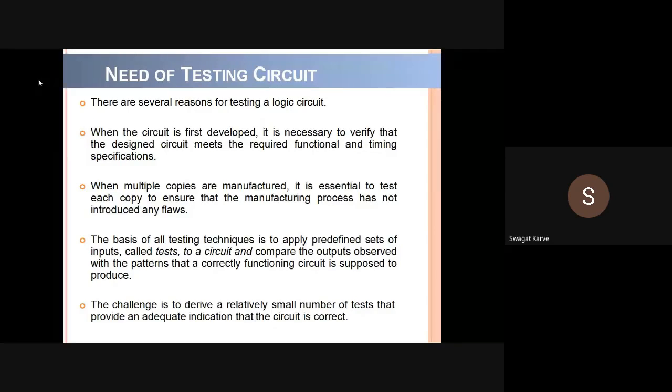राईट. Now we will have the third test set. In that we have given logic 1 input to 4 pins and logic 0 to the remaining 4 pins, and now I will observe the output pattern. बरोबर आहे. Likewise, you can design n number of test sets and apply them to that particular IC and observe the output.